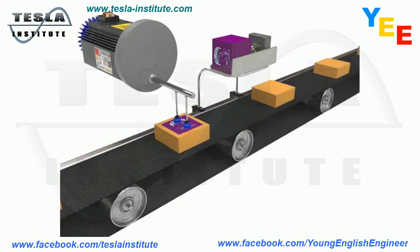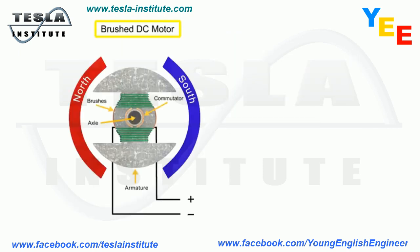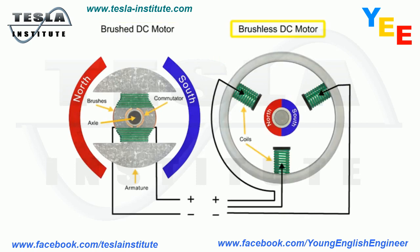For this exercise, we'll discover the basics of stepper motor technology, beginning with the brushless DC motor. Unlike DC brush motors, DC brushless motors do not utilize brushes to control current. Permanent magnets bonded directly to the rotor of the brushless DC motor create rotational motion as current passes through the stator.